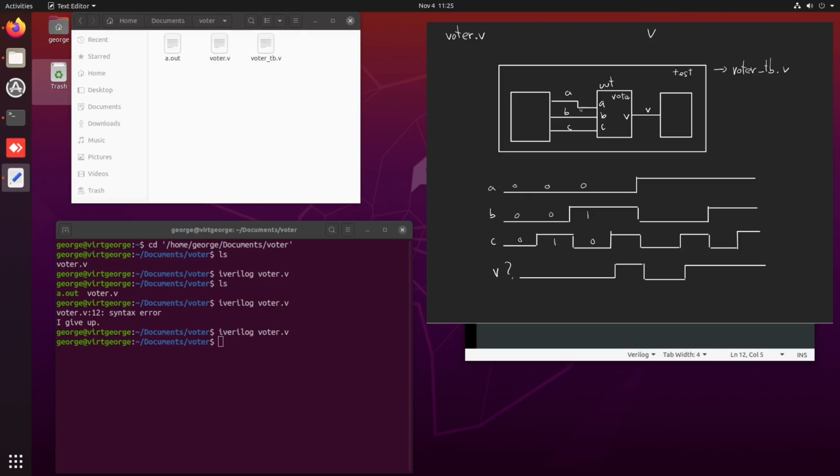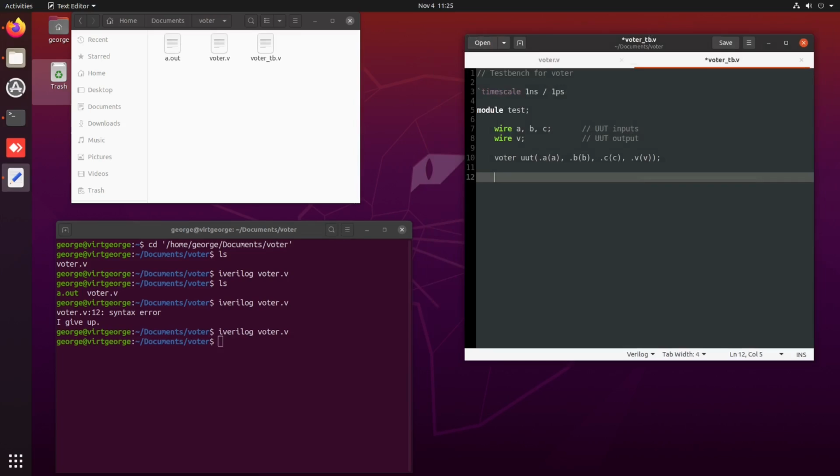Because we are going to use a procedural description, we need to correct something, which is to change these signals to type reg. Reg is the type that we use for variables in Verilog, and variables are the signals that we can assign in a procedural description.